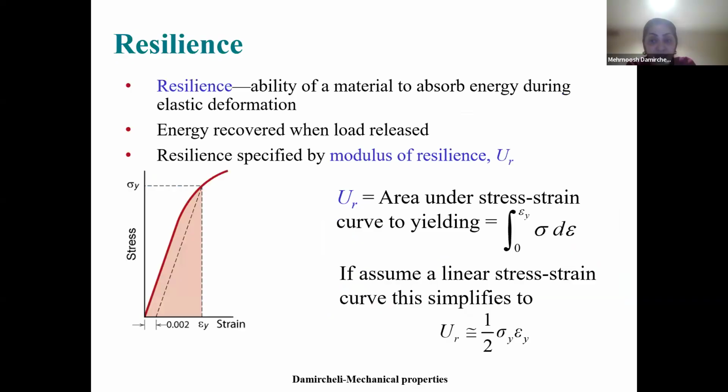Modulus of resilience is the material's property to absorb energy in the elastic regions and return it upon unloading. It is represented by the area under the elastic portion of the stress-strain curve. It means that if we know sigma y, look here, it is an approximation. We cannot say exactly this, but if you see the difference I show.